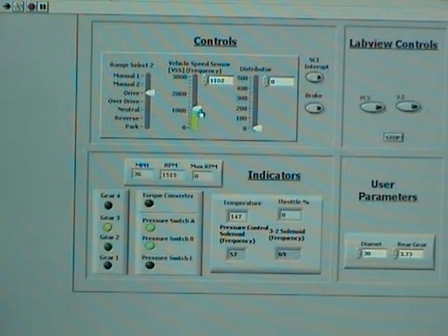And now we'll go ahead and go through the whole range, and there's 3. And then again, you'll see that 4th gear is not allowed. So if we go to manual 2, you'll see that we have an instantaneous jump to gear 2. You would not do that intentionally going down the road. That's something that you put the range select into whenever you're towing. And also the transmission is going to override the shift solenoids mechanically anyway. It's going to put itself into gear 2.